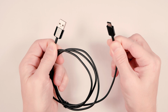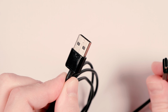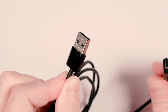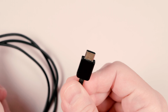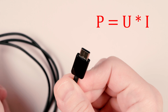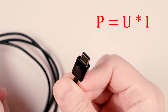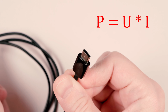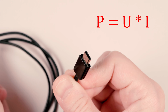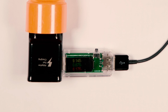Modern smartphones have powerful processors and batteries of large capacity. And the current that can be transmitted through a standard USB cable is not enough to charge them quickly. But charging requires power, not current. And power is the product of voltage and current. If we cannot increase the current, its value depends, as mentioned above, on the wire gauge, nothing prevents us from increasing the voltage. This is exactly what we observe in the so-called fast charging mode.